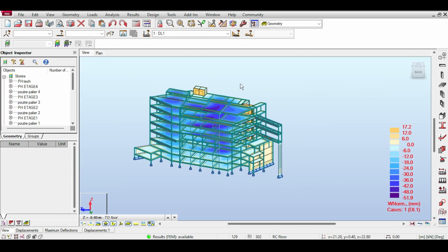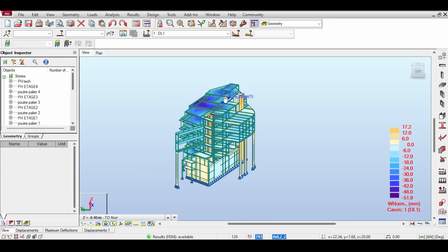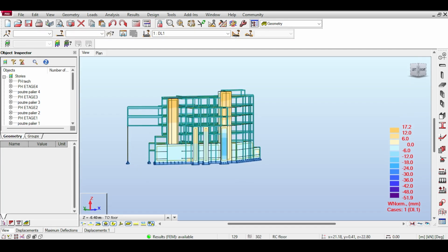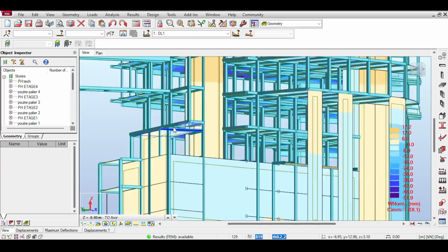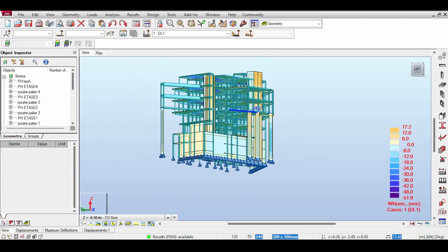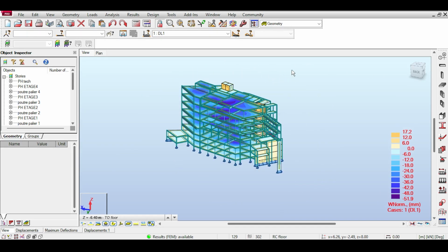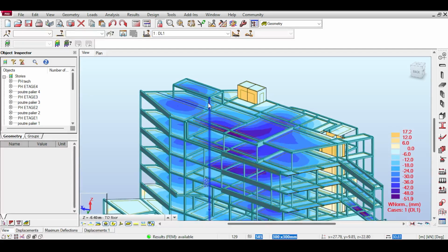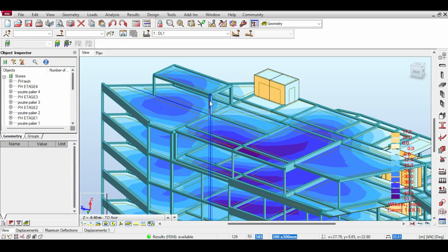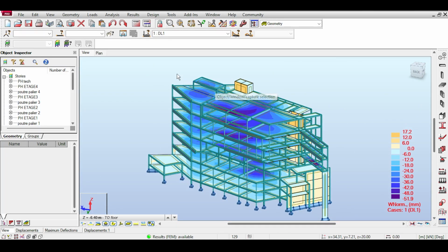So, okay, let me recap the points of interest I have for him. First of all, you have some problems with your meshing systems. You are not aligning your walls perfectly. Secondly, you have too many cantilevers that don't have any purpose except being cantilevers, and the beams there are very weak. Thirdly, your load path is extremely incorrect. The loads are not being carried all the way to the ground. Fourth point is, there are some inconsistencies in the meshing. For example, this column was unable to carry the slab because there was a misalignment, and this might be the case in multiple places. And of course, finally, you have some stiffness issues that need solving.